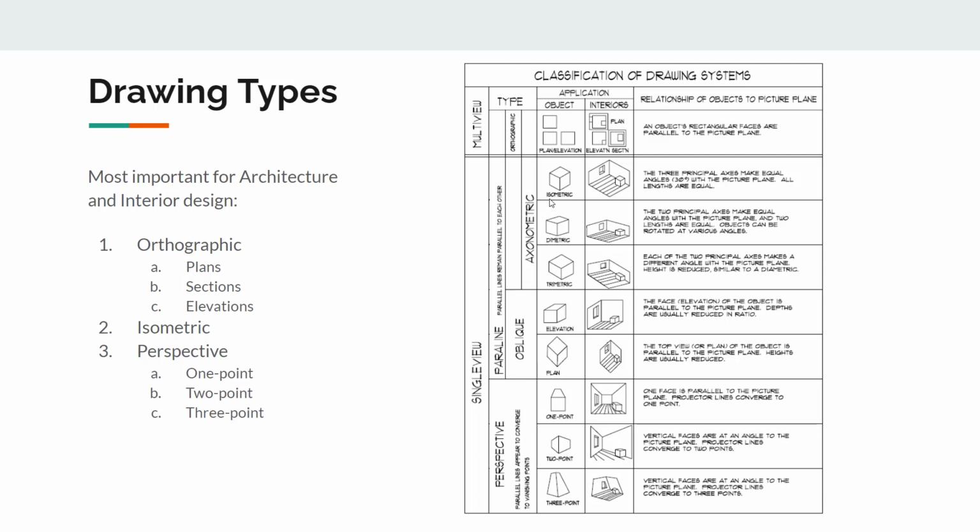Okay, so an isometric drawing, good example of it right here, just a cube, and the focus point is right on this central intersection at the corner. And every single line is drawn at the same scale, okay? If you look down, you can see what I mean by that, how there's some distortion that's going on here. Not every single face is represented the same way, but in an isometric drawing, each face of the object receives an equal level of emphasis, okay?